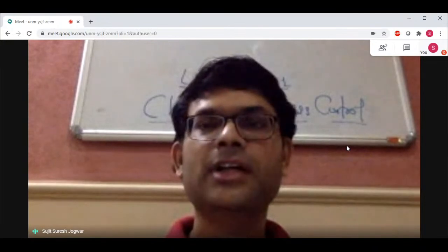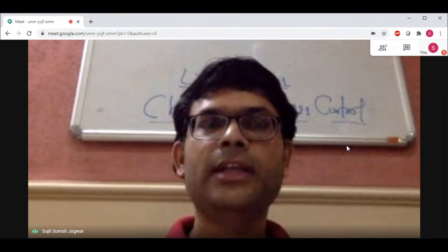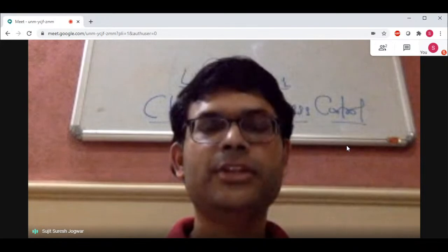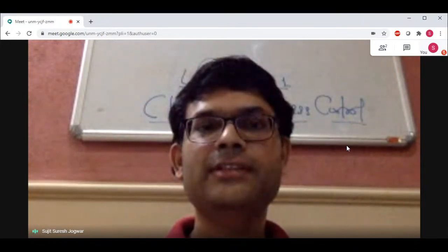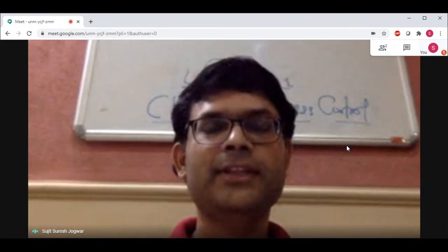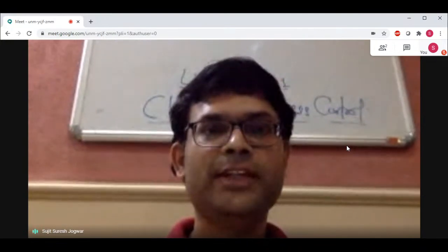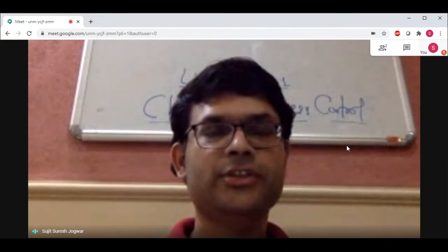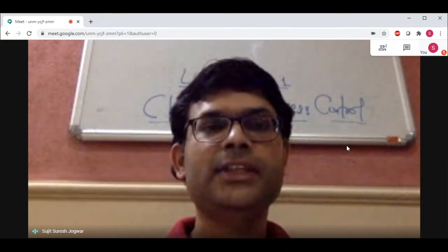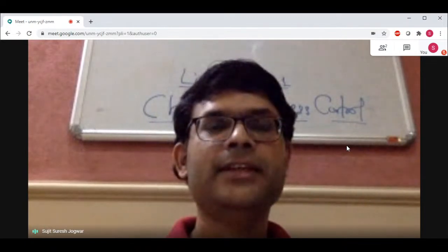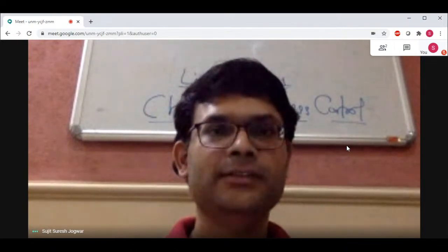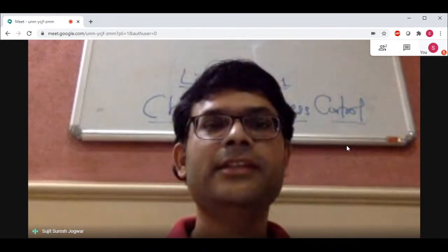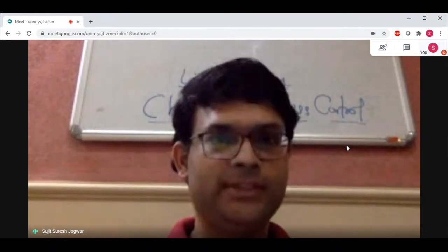Now zeros tell you the relative contribution of these dynamic modes. In the transfer function I told you, 1 over (s minus 1)(s minus 2), there is no zero, because the numerator is just a constant, not a function of s. But if I put something in the numerator, let us say s plus 1, then the zero of the system is going to be at minus 1.